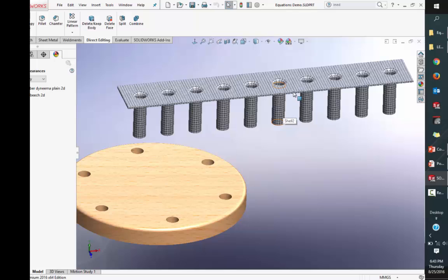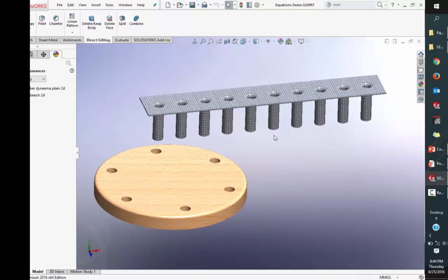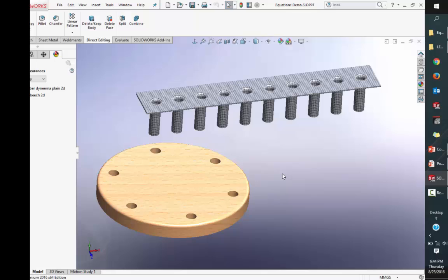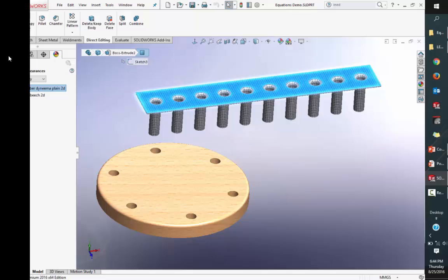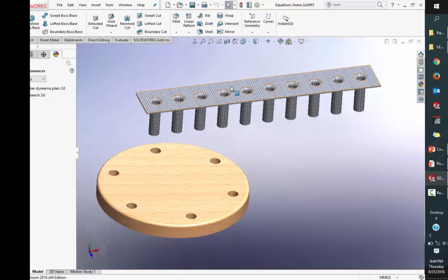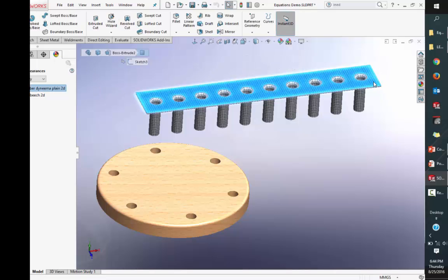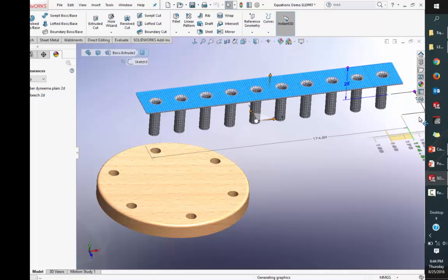All right, so new functionality inside of SOLIDWORKS we got a couple years ago is the ability to adjust a pattern based on length, or adjust the quantity or the spacing. It's something that I will say I've created a lot of equations for. You take the length, you subtract this, you divide by this, you minus 1 because for whatever reason we have to, and eventually we could get something that we could come in here and very easily sketch or stretch, and we would have the ability to update the pattern as necessary.